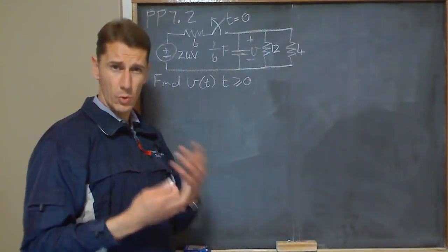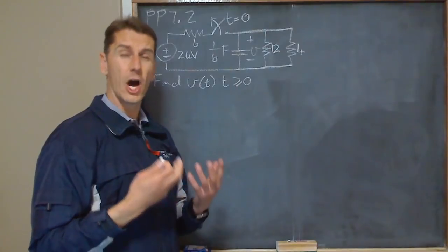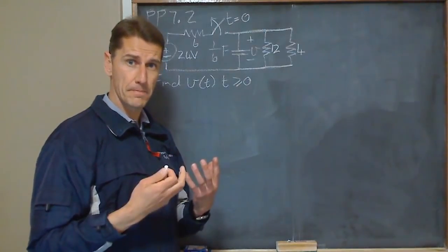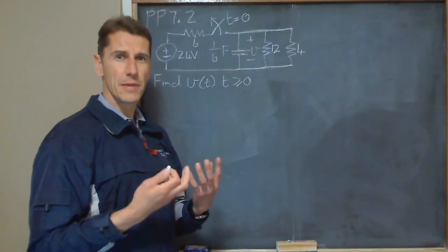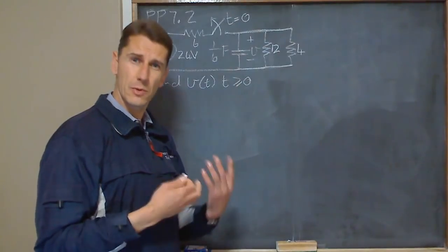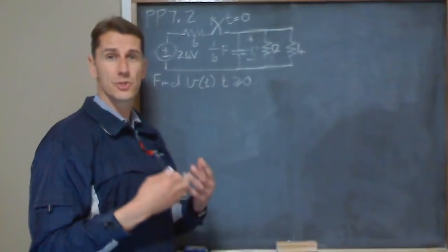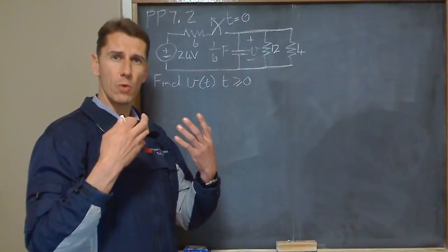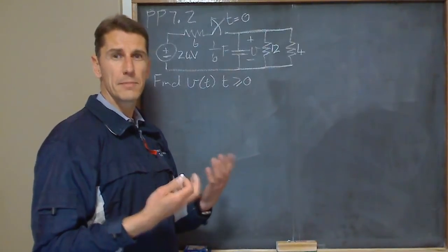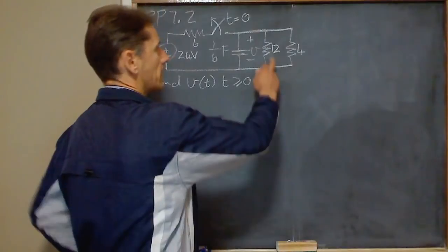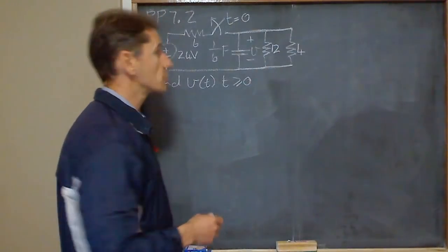It becomes an open circuit. Okay, it charges up and the voltage becomes a certain value that we're going to need to calculate now. And when it's all charged up, you can't have any more current flowing through it and it becomes an open circuit. And then we're left with those two resistors, the 12 and the 4.